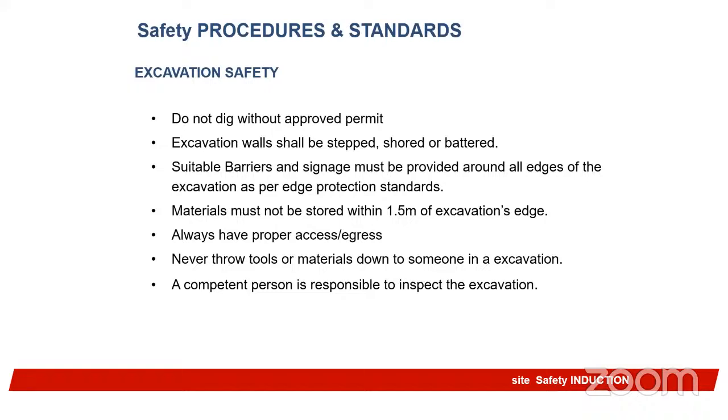The purpose is that if it's too straight and just deep like that, the edges are very weak, and the distance from that edge to the ground can be as high as 1 or 2 meters, and the impact will be higher. But when it is sloped, even if something wants to fall, it rolls down, and it is not directly under the edge, the inner edge of the work activity.